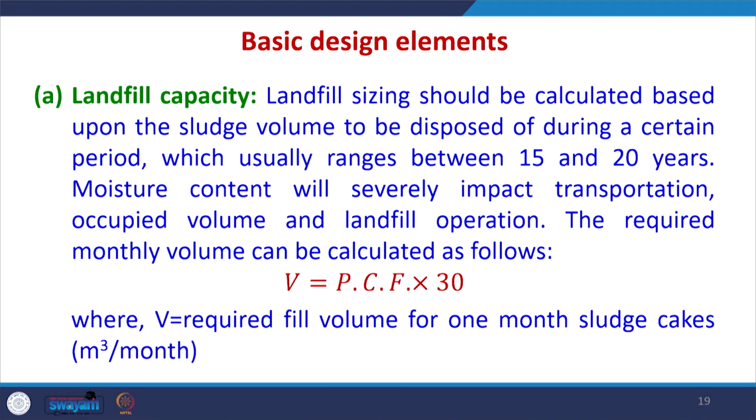Now, there are certainly basic design elements with respect to landfill. So, we are going to study them. First is the landfill capacity. The landfill sizing should be calculated based upon the sludge volume to be disposed of during a certain period, usually ranging from 15 to 20 years. So, how much sludge is getting generated and for how much time this landfill can be operated.